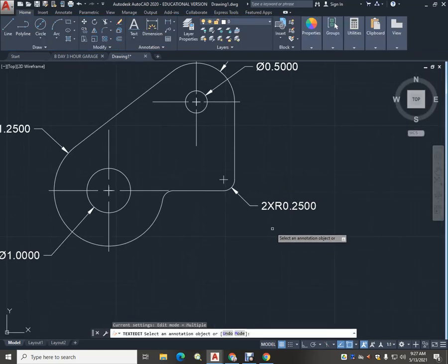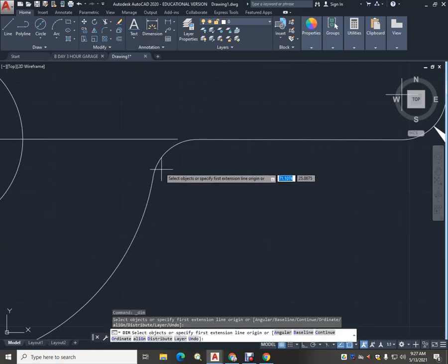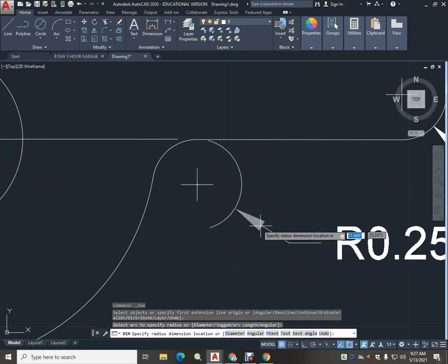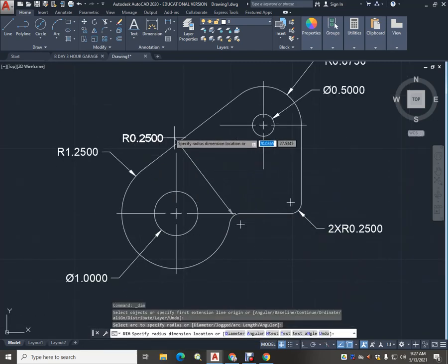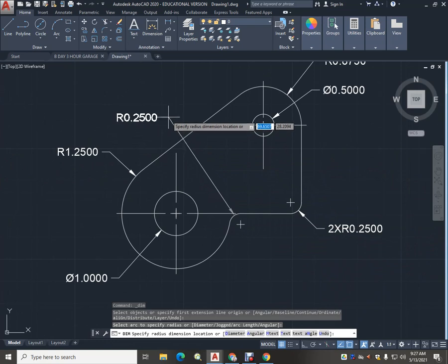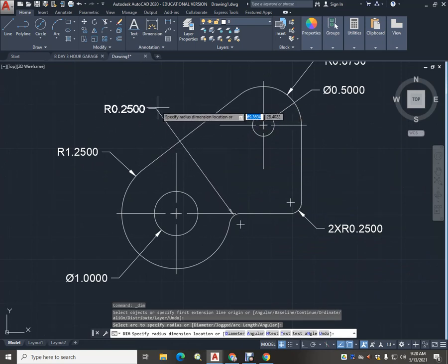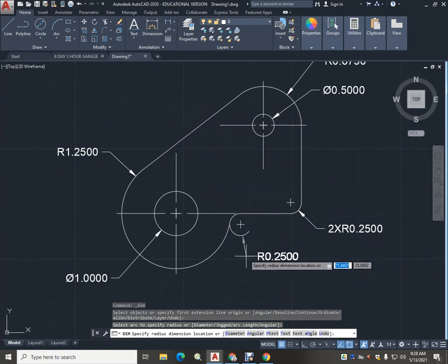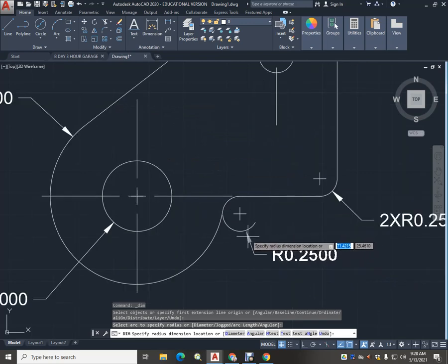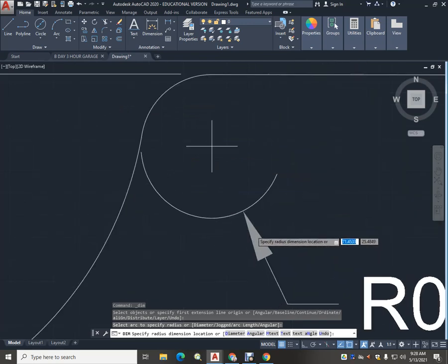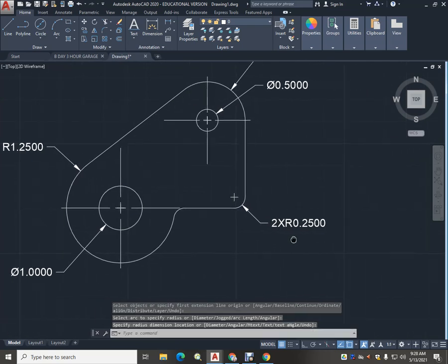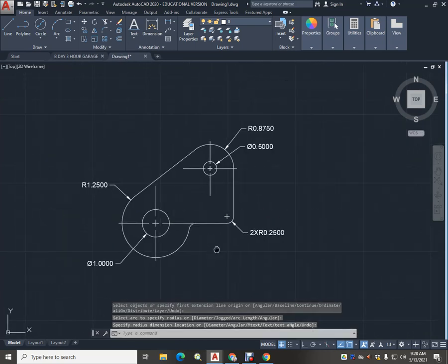So there it throws it out that we have 2 of those rather than dimensioning it, which would be kind of a weird one. It will, like I said before, give us that dimension, but it really likes to have it right on the corner like that. If I were to actually do it, I might throw it way up here so it looks better, but it gives you that little extension line, which is okay, but I can easily enough just call it out as 2 times.